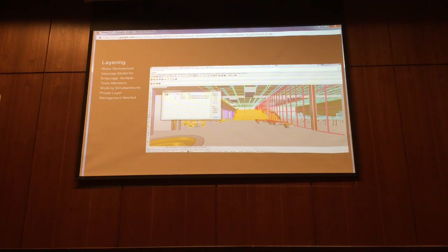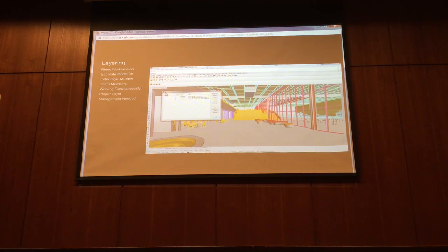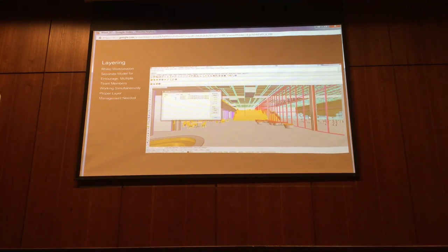You can also, one thing I recommend looking into, it's not necessary for this class, but you can have work sessions in Rhino. A work session is a separate Rhino model. I was working with someone else, where I was modeling the building and he placed all the furniture. We had the same origin point, so I could just bring all of that file into my file, with all the materials mapped, and render it. So you can work session multiple models into the same model and render everything.